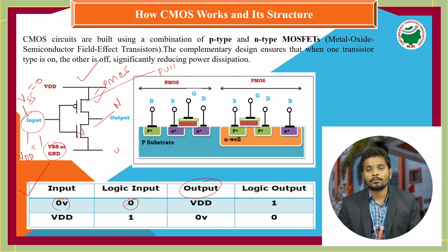As you know, for constructing NMOS, as said earlier, we take a P substrate, and for PMOS we take an N substrate. The CMOS is the combination of NMOS and PMOS, so which substrate do we need? If you want to fabricate PMOS, we take an N substrate, and for NMOS we take a P substrate. But CMOS is the combination of both, so we have to take a substrate having good compatibility for both.